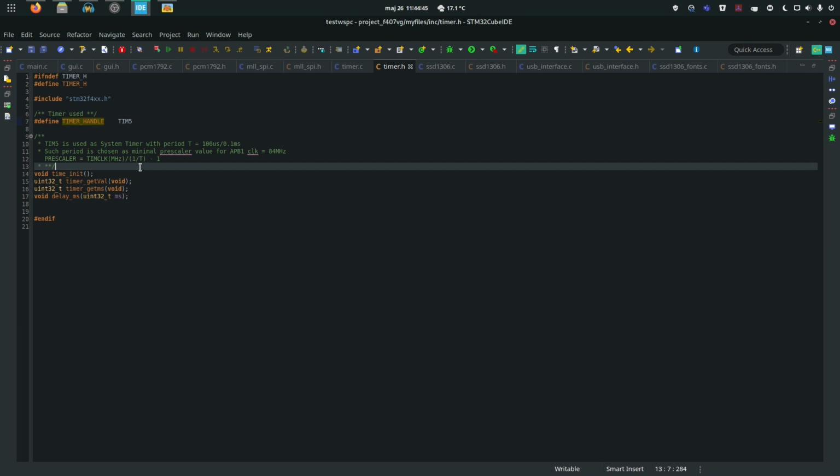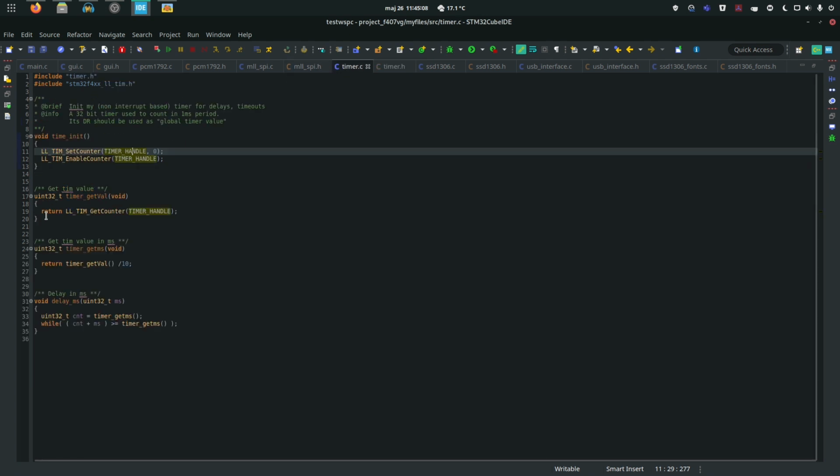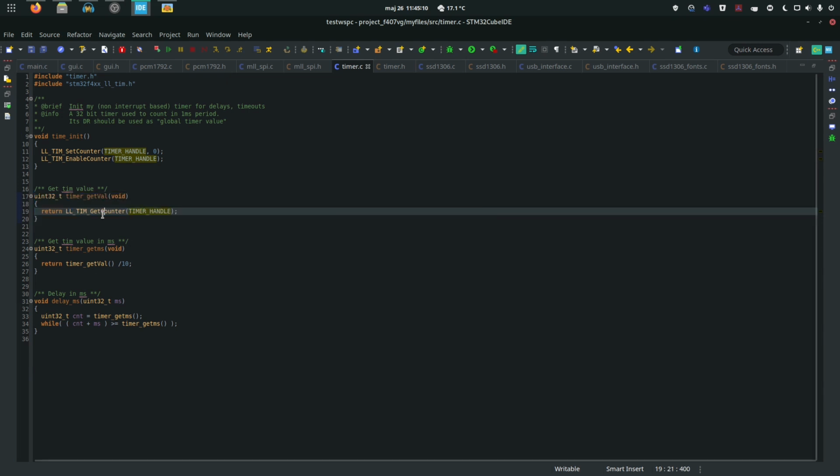So that interrupt routine just increments a global variable that stores the milliseconds since the timer was started. And this is unacceptable because I cannot have any interrupts. So the only way I can do it is to have a 32-bit timer that has a data register of 32 bits and counts in the background regardless of operation, and when I want to know the time right now, I can just call one of these functions called timerGetValue to return the value from the timer.